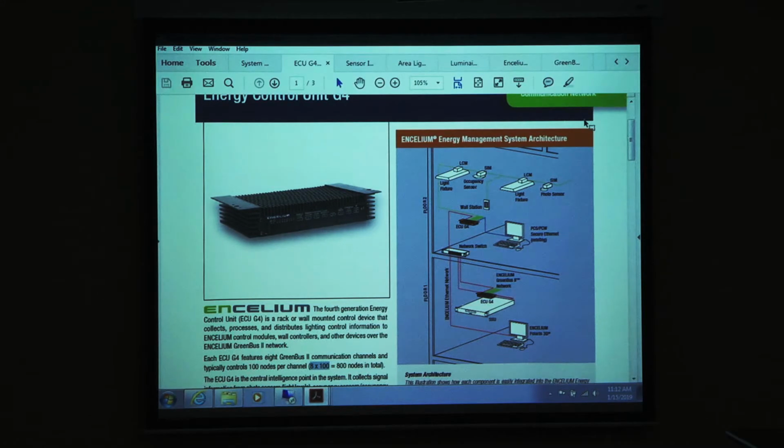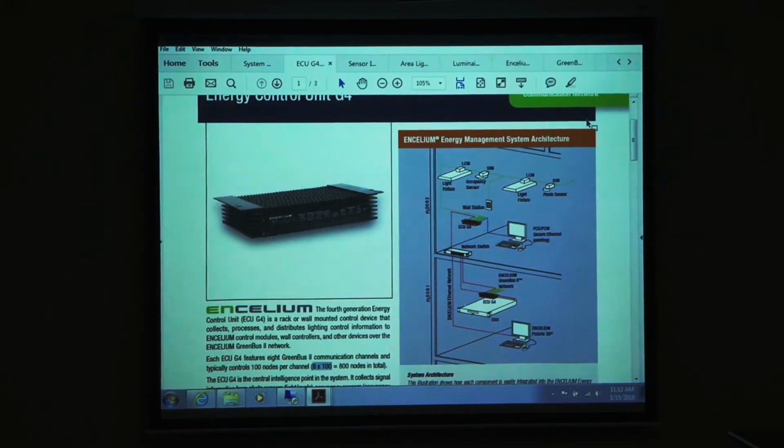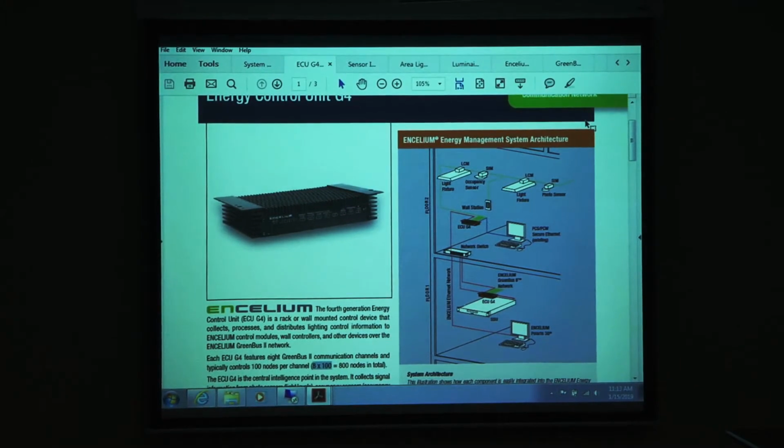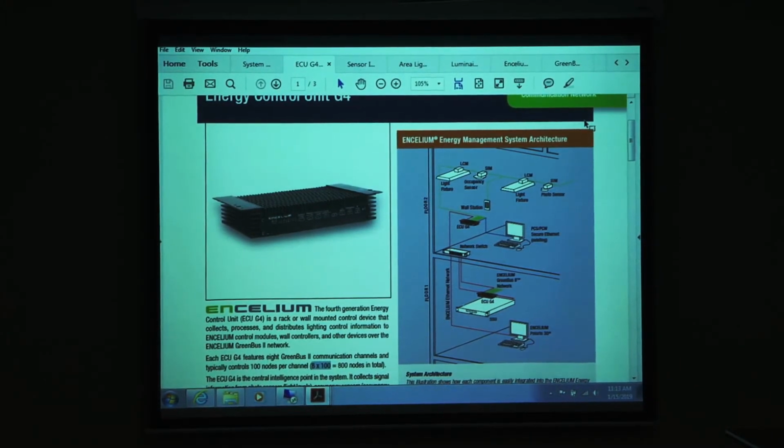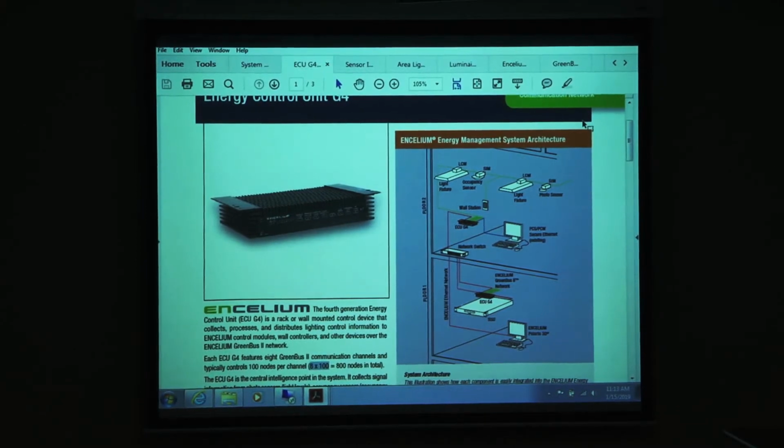The application guys in the office use a voltage calculator device, pretty much an Excel spreadsheet with formulas in the back of it. Every device that we have has a certain current draw. For example, if they put in a 30 milliamp aux sensor, that's one. You put in another 30 milliamp, that's 60 milliamps. So it keeps adding up.